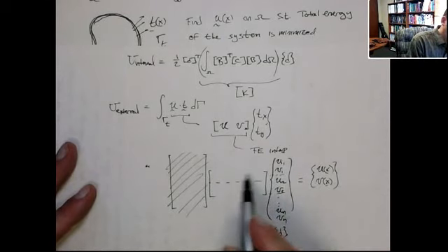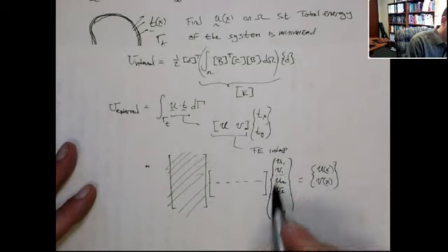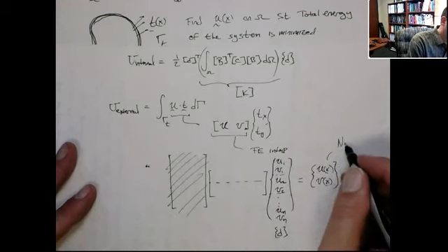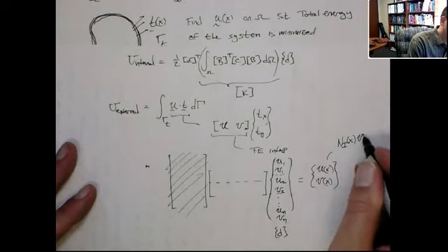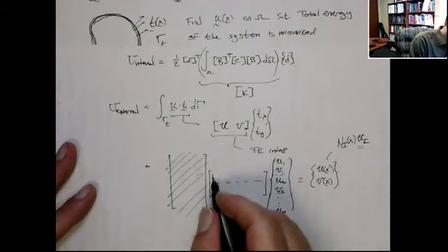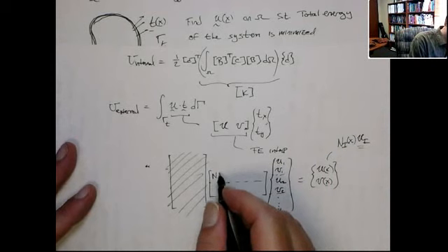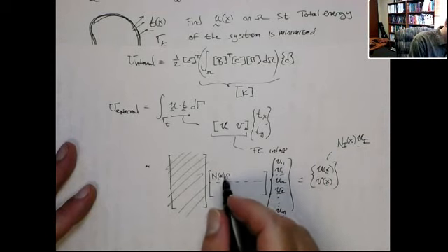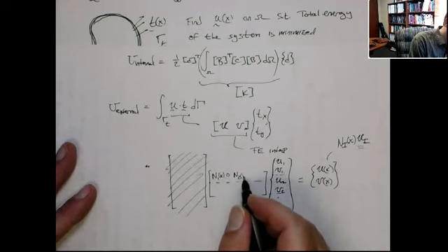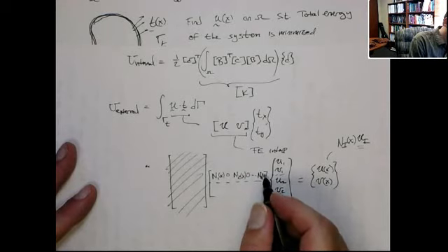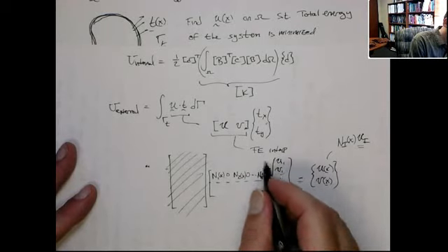Now, this top row gets multiplied by the displacement vector and should give me the u's. Well, we know that this needs to be the N_i's times the nodal unknowns, the x nodal unknowns. It only involves the x degrees of freedom. So everywhere you have the y's, it should be 0. And everywhere you have the x's, you should get the shape function. So it should be something like this. N1 of x times 0, and then 0. And then N2 of x and 0, and so on and so forth, until you get N_n of x, and then in here is a 0.